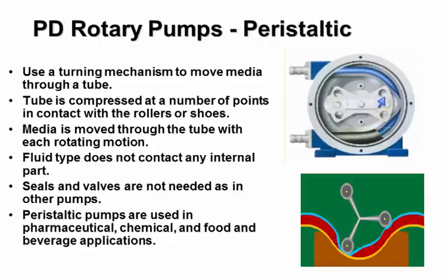So I've had one answer, and that's from Charles. He says that we can see these handling slurries, light slurries. When I say light slurries, you have to bear in mind we're normally talking about chemical slurries, not mining slurries. The problem is that when the rotor turns, it squeezes this flexible tube. If we had any sizable solids in there, the tube would get damaged.